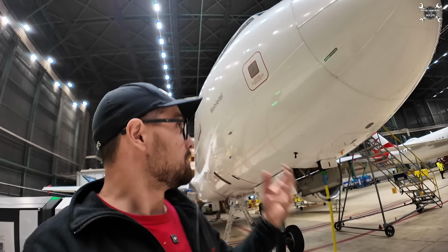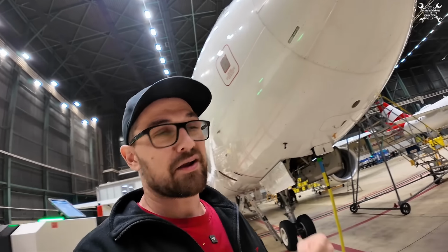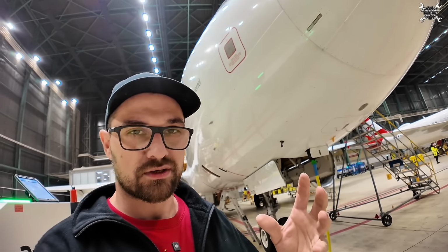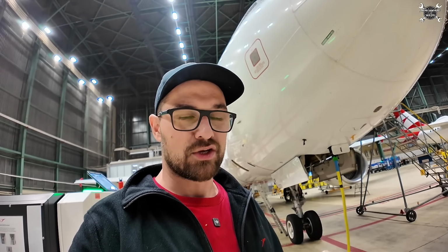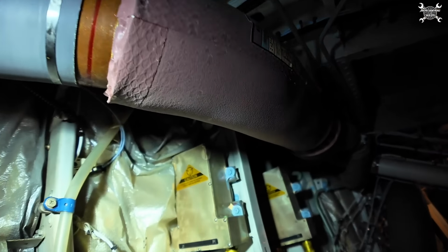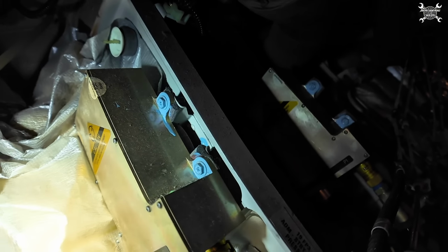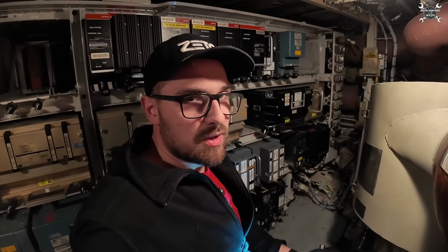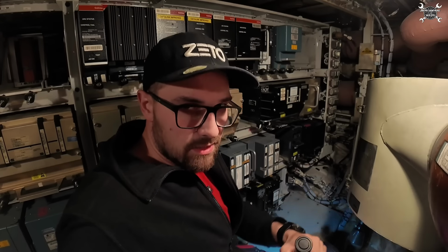Okay, and how does it work? Pitot probes and static ports are here basically only to guide air or provide pressure for the sensors. And sensors are your translators. They transfer the information, which is pressure, to a digital signal. And this all happens in the component which is called Air Data Module. And each of the ports, which you can see out there, has one. These air data modules you can find very close to the probes, but they are inside of the airplane.